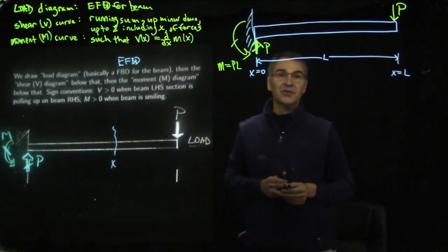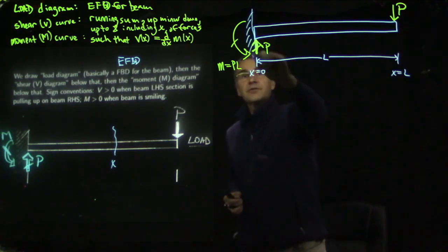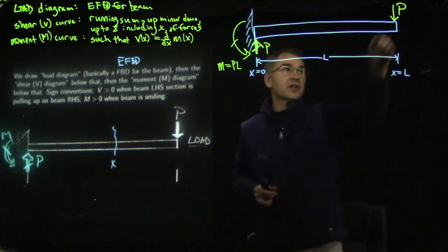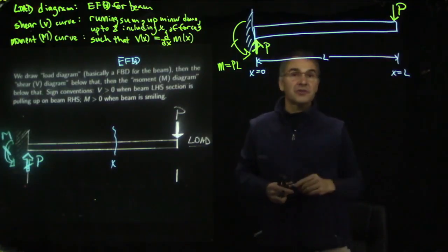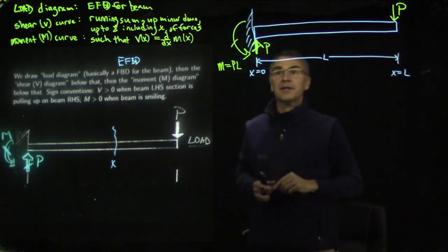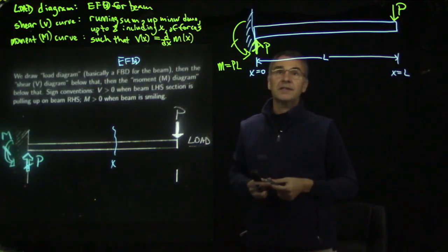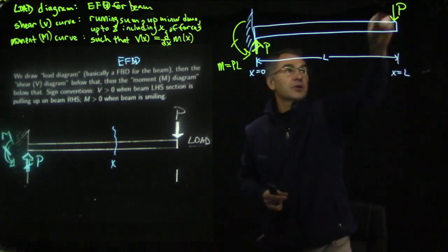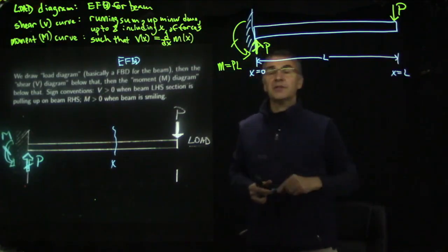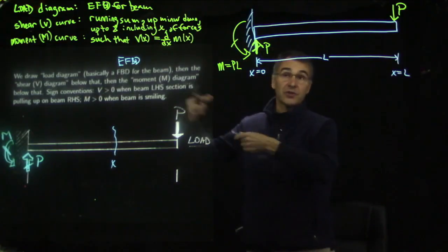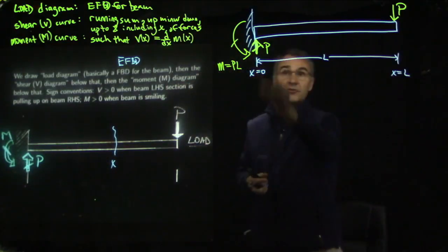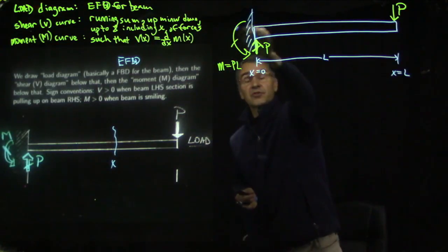And this is, again, easier to understand through examples, I think. The little slash mark through this force line means it's a reaction force. In other words, it's not a load that is the beam's raison d'etre. It is a force, or in this case, a moment or torque exerted by the wall, or by the support, needed to hold the beam up. So this load is what the beam is holding up, and these so-called reactions, the reaction force and the reaction moment, are what is needed by the rest of the structure to hold this beam up. So the rest of the structure, in this case the wall that the cantilever is attached to, has to exert this upward force, and it has to exert this counterclockwise moment.